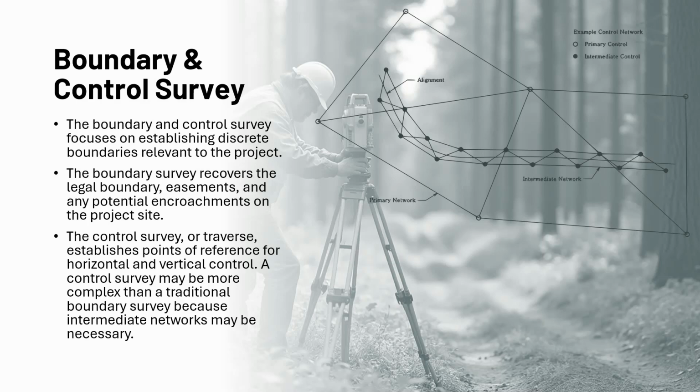At that point, you need to know about your adjoiners and restrictions and right-of-ways and easements and things like that. Potential agreements between past landowners to where maybe an encroachment is not technically an encroachment. It's a handshake deal. And in Texas, the handshake rules apply. That is a legal binding agreement. So you have to make sure you investigate all of that information at this time.